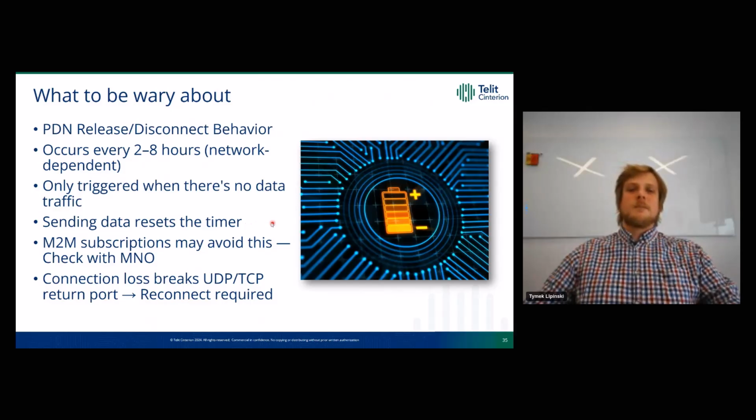This usually happens with, let's say, normal consumer SIM cards, the typical internet SIM cards available in shops. We can beat around this problem using a dedicated M2M, machine-to-machine, subscription from our operators, but we have to check with them. Please, every time, remember to check with the mobile operator whether for any reason they have enabled or disabled the PDN disconnect when there is no data traffic, even on M2M SIM cards.